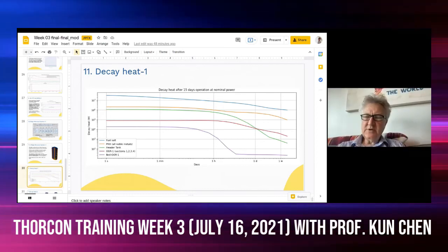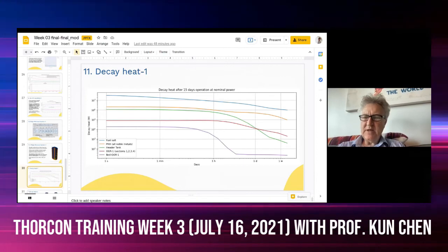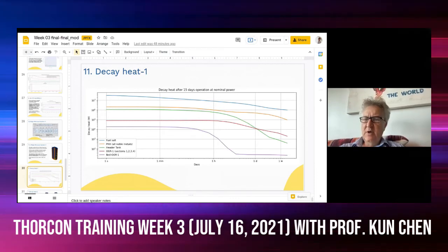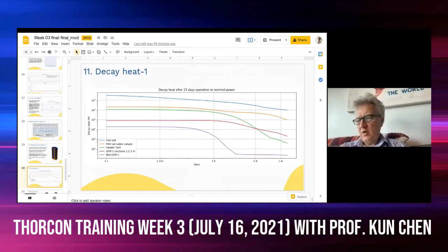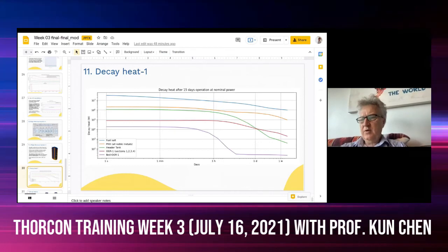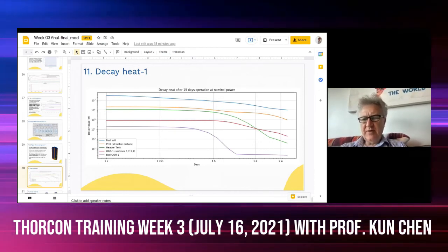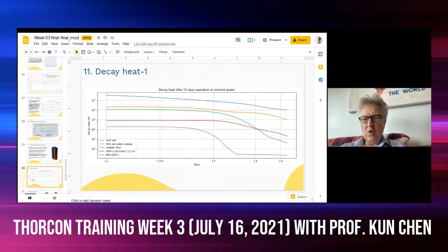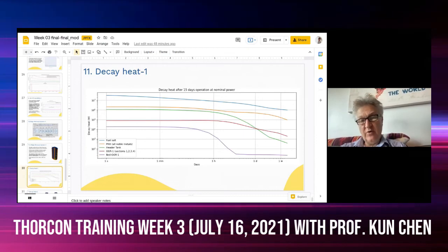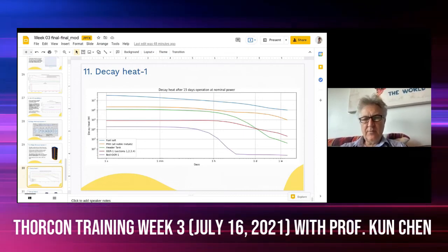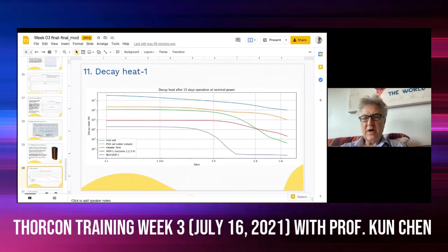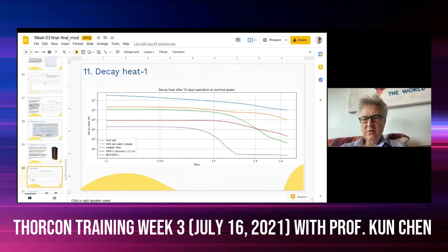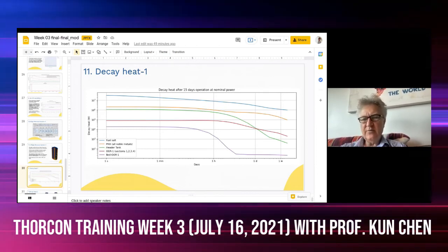That's mostly sufficient. We have flow both in the gaps and in the holes. The holes don't change size very much. So we have to balance: when the gaps get larger, the salt coming out of the gaps goes up in temperature a little, and the pressure drop in the whole core drops down. So the flow in the holes goes down. But you get mixing at the top to balance out the slight changes in temperature. We're talking about changes in temperature on the order of 5 to 10 degrees.